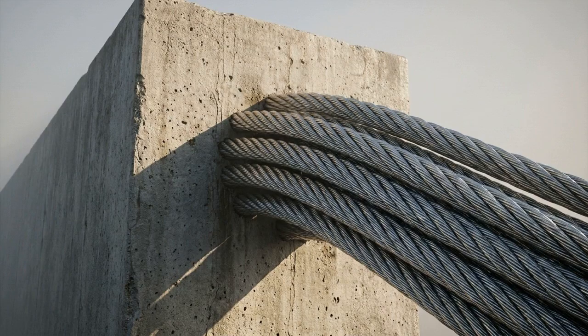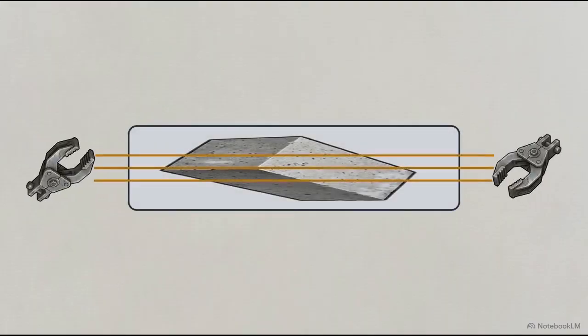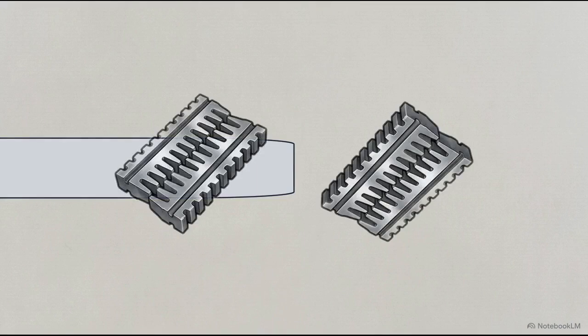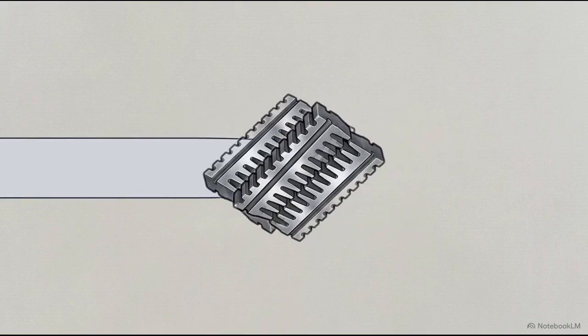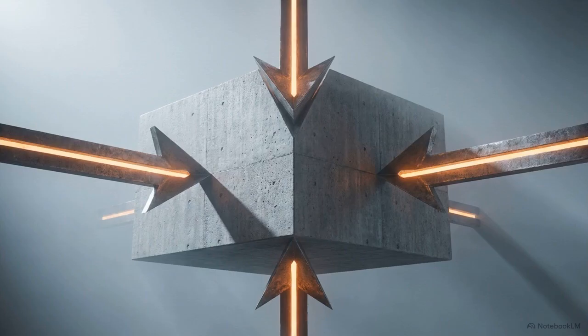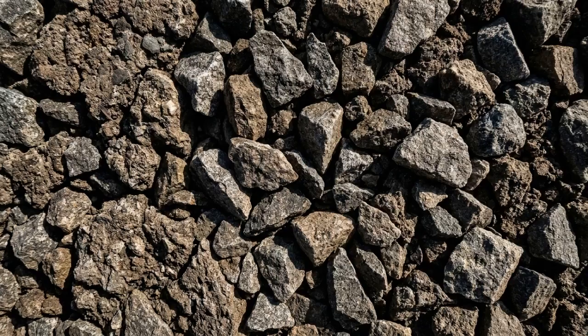Pre-stressed concrete, or PSC pavements, rewrite the rules even further. By running high-tensile steel cables through the slab and pulling them tight, PSC creates extreme internal compression. This compression overrides the natural thermal expansion forces, allowing for massive continuous slabs of up to 140 meters in length, punctuated only by specialized steel plate expansion joints at the extreme ends. The dimensions in Table 1 are not arbitrary limits. They are a calculated equilibrium, balancing the concrete type, the internal reinforcement strategy, and subgrade frictional drag.